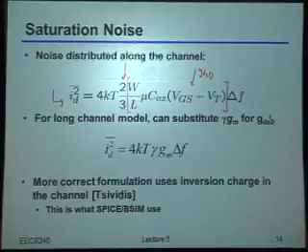Okay? And in particular, this is working out because it turns out that for a long channel device, GM is just equal to GDS naught. Okay? At least ignoring channel length modulation and things like that. And by the way, if you don't believe me, just look at the expression above. You'll see indeed that's exactly what GM would be.